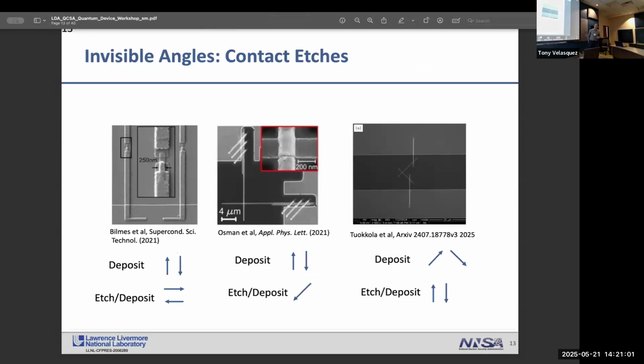So back to the qubit fabrication world. So you have to do deposition of aluminum at different angles, and a more mundane but quite important process is that you have to form good electrical contact between the Josephson junction and the superconductor that forms the rest of the circuit. So there are three approaches to this. You can either put one big swatch of aluminum over your contact in a second lithography step.